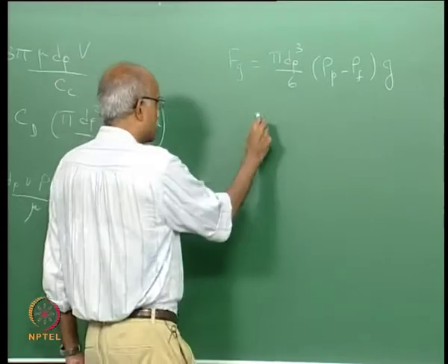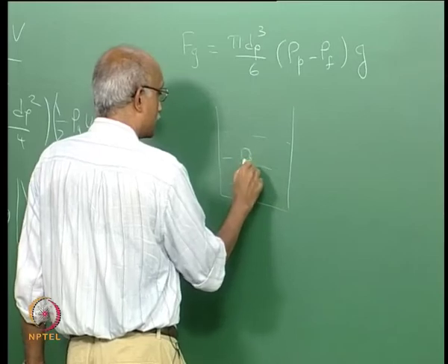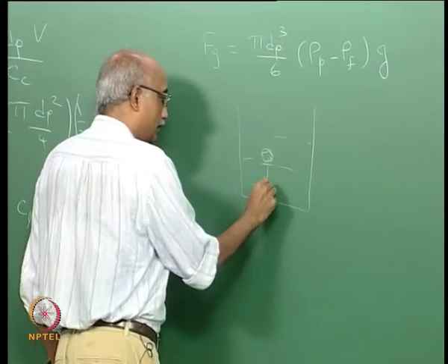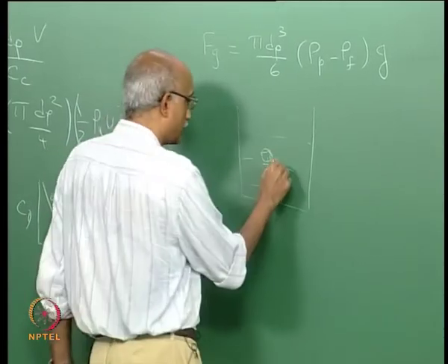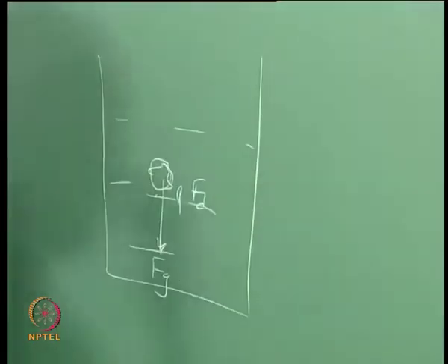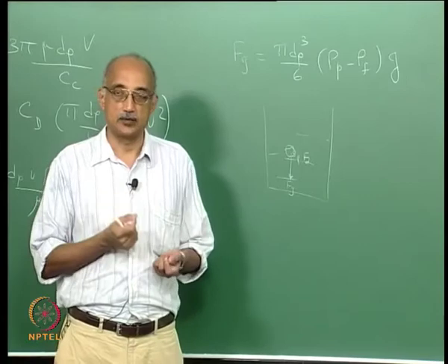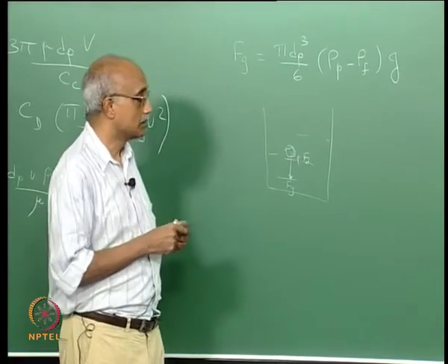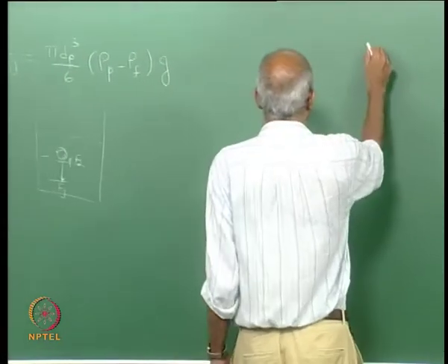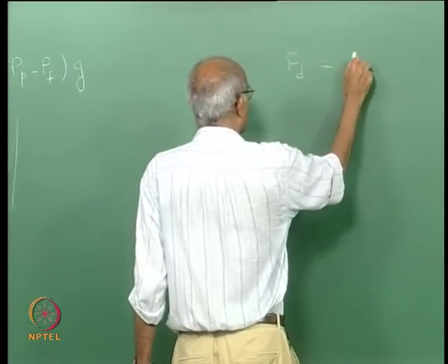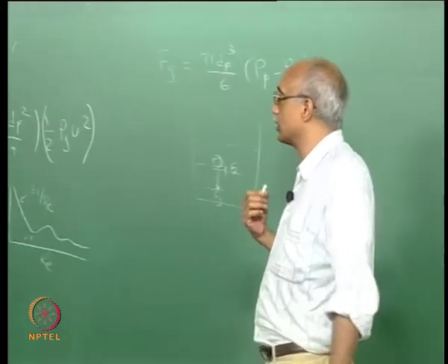Now, in the case where you have sedimentation occurring, where particles are suspended in a fluid, the gravitational force Fg is acting in this direction and the drag force is essentially opposing it, and because of that the particle reaches what is known as a settling velocity or a terminal velocity. The expression for that can be obtained essentially by equating Fd to Fg.